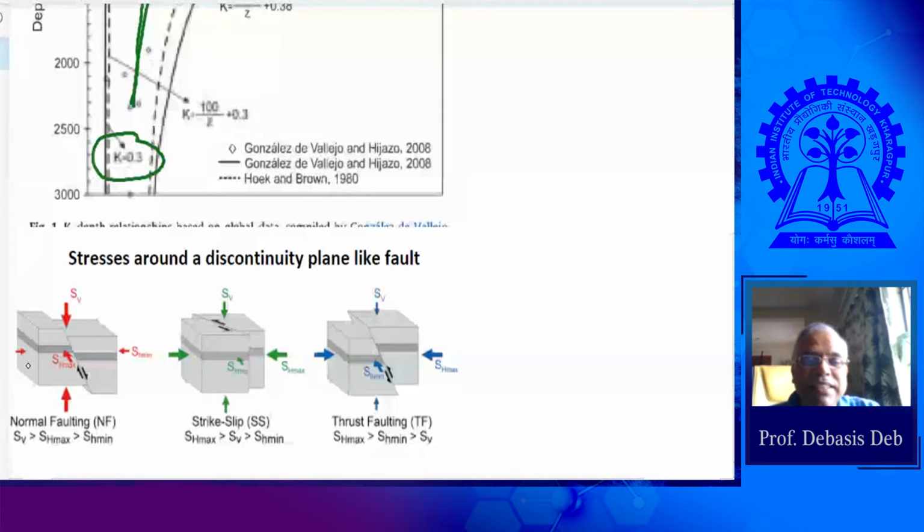That means after the structure is made, the stress will come on it. Think of any engineering branch, this is what it is. After the product is made or a structure is built, then the stress will come. In mining engineering, the beauty is stress is already there. We call them in situ stresses. We are going there to disturb it. This is the difference.